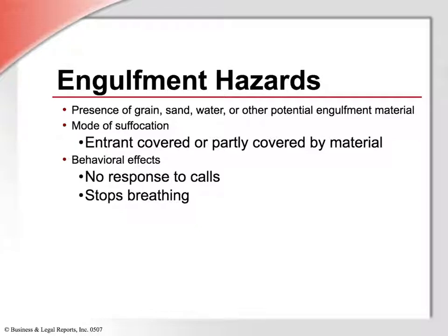You need to know the hazards of the confined space that an entrant might face. And the first one is engulfment hazards. When there's grain, sand, water, or other potential engulfment materials present, the mode of suffocation is that the entrant is covered or partly covered by material. Behavioral aspects are no response to calls, or he stops breathing.